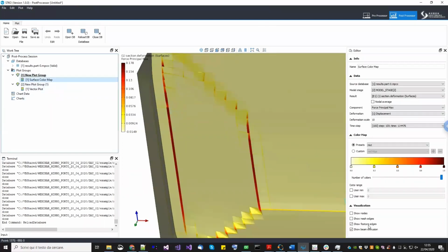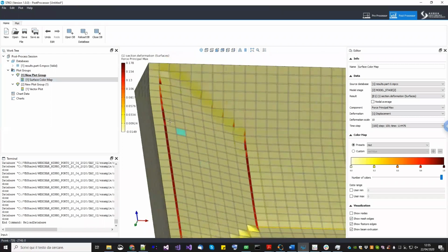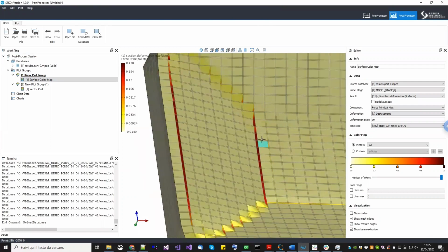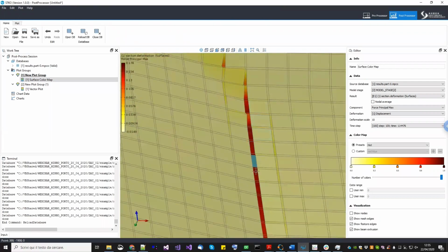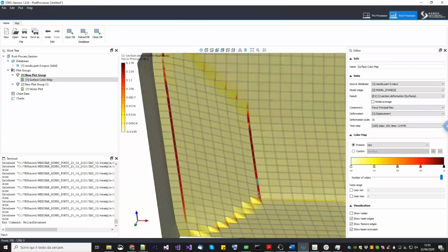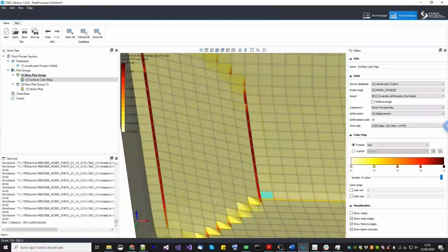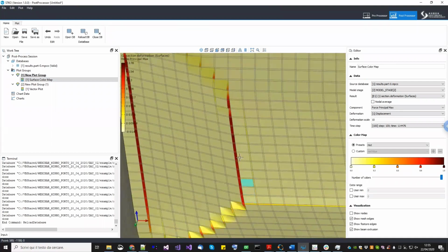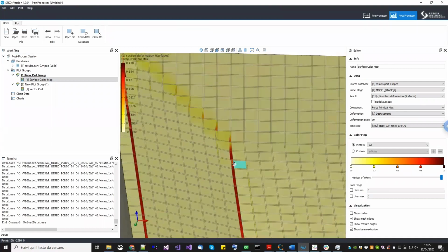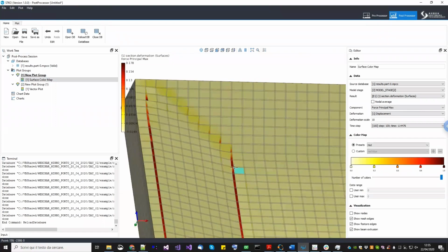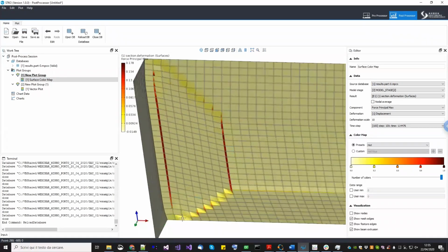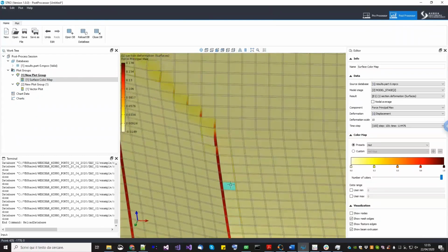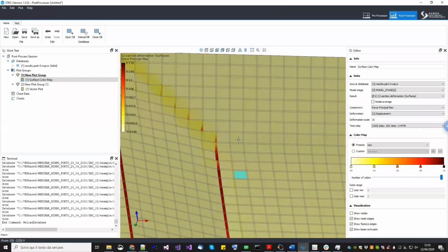Basically, let me switch on the mesh edges. Here we see complete lines making the entire wall fail both in mortar joints and bricks. Why? Because of course, if the mortar joint cannot fail in the out of plane direction, they cannot create a complete crack. So the crack should pass through the brick. So it makes the mortar joint much stiffer than before. And so the only failure that you can see is a bending failure, not a transverse shear failure like it happened in the thick shell theory.